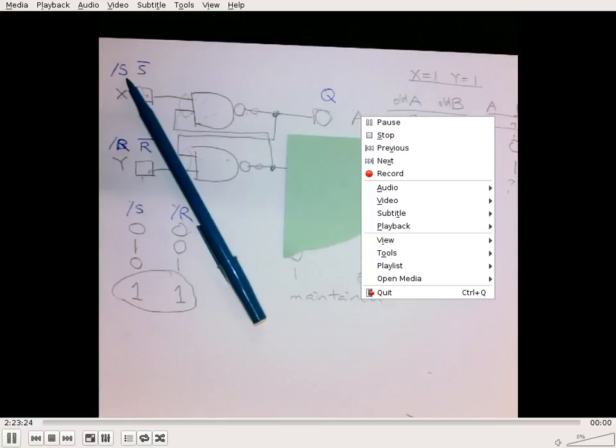So the brownout detection circuit is really, really important because the worst thing that can happen to a computer is not a blackout. A blackout is a clean cut of no power. Okay, you just lose all power and that's the end of it. No power, the computer stops working. No big deal. A brownout, on the other hand, means you're losing some power.